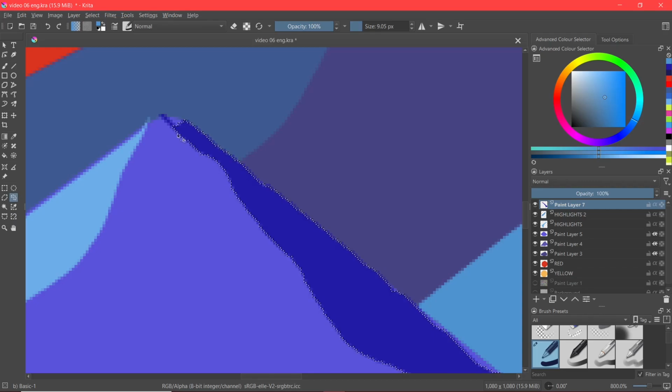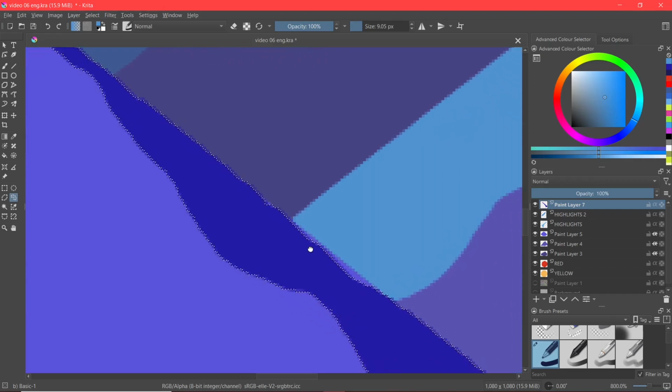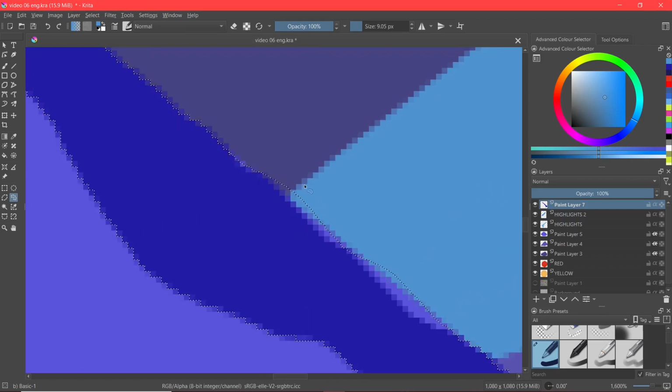From here we can add this part, for example. Always remember to close it. This little section here, we can move down in our page and see that this isn't selected. So again, first click the shift key and then start drawing. And if we make a mistake, all we need to do is click our Alt key and take out the bits that we don't need.